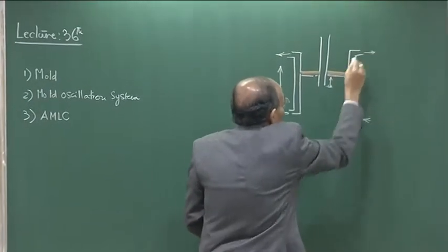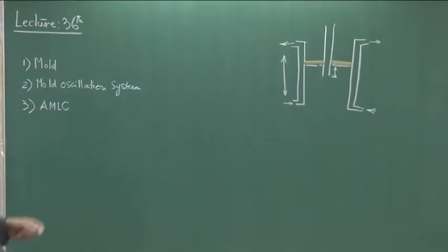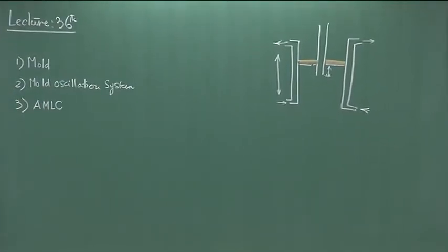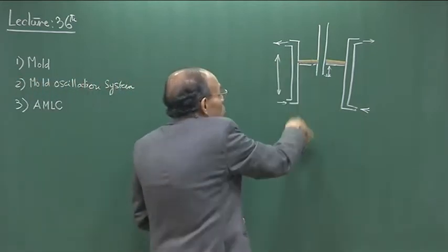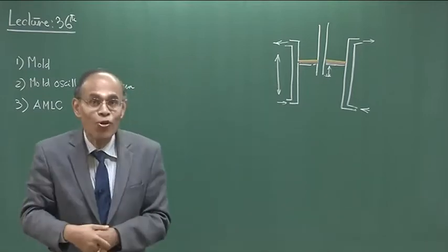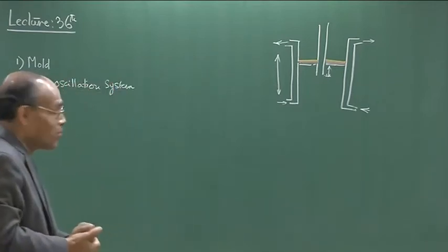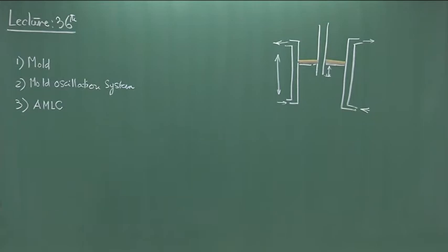So, these are water cooling. That is the automatic mold level controller, which is very important, and it also tells us that if the mold level fluctuates too much, something is going wrong upstream. One such possibility, as I have indicated, is that if the mold level goes down continuously, it is an indication that possibly there has been deposition of inclusions in the tundish nozzle and so on.